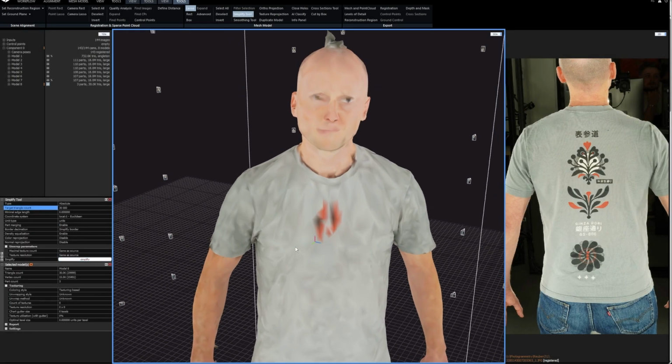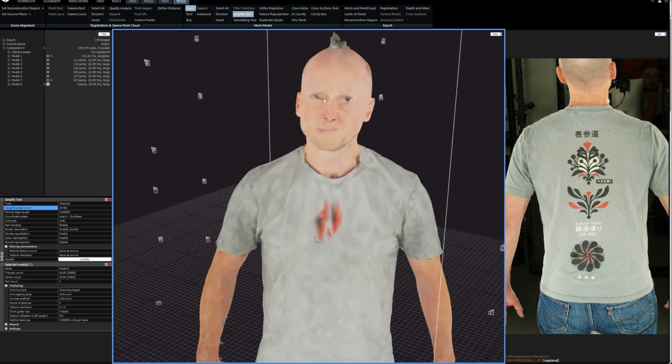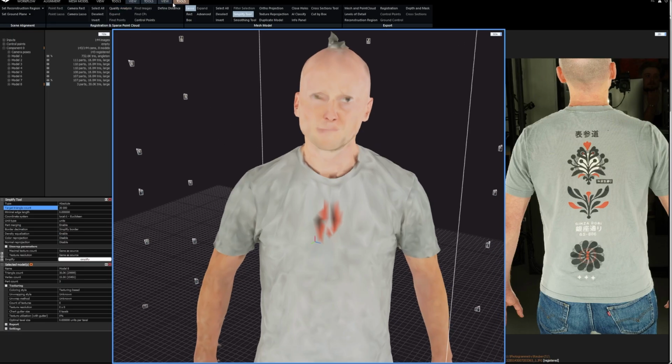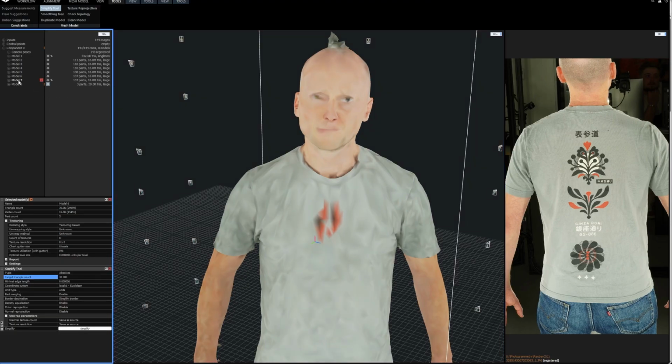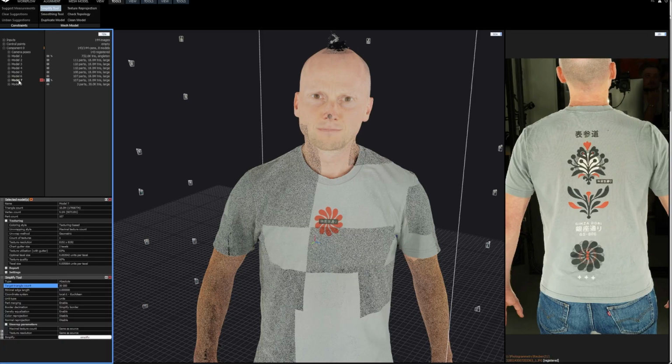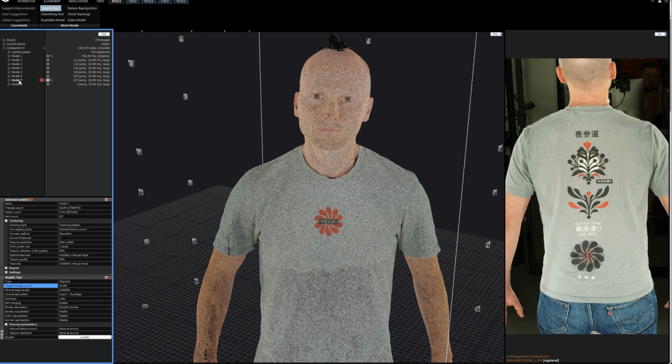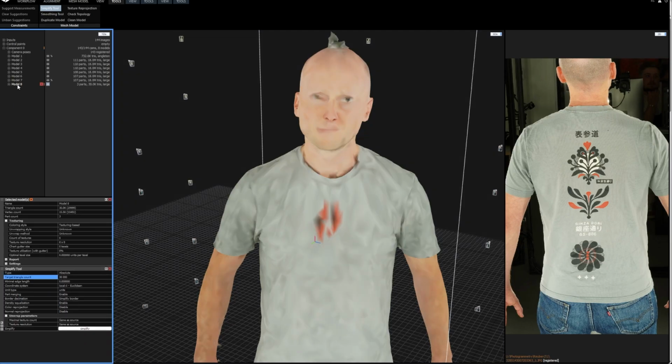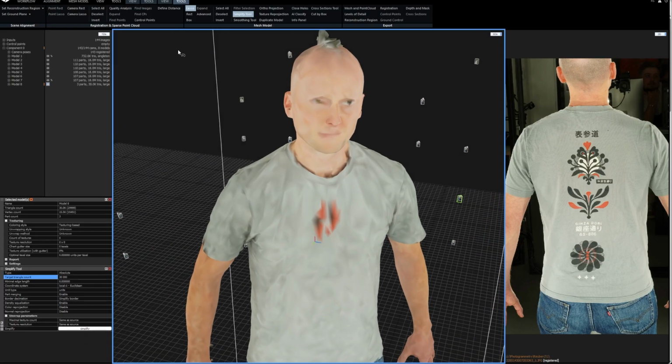And there we go. Because it's not textured anymore, if you make changes to the underlying mesh of a 3D model, the UVs will be changed so that you would have to reproject the textures onto it. But we'll go over that in a second. So this has created a new model that's 30,000 triangles, and you can compare that to the high resolution one there, if you can click between them. So there's the high resolution one, and there's the 30,000 one that we've created.